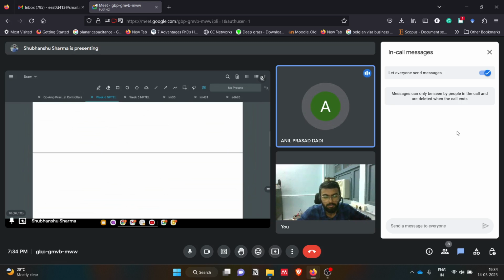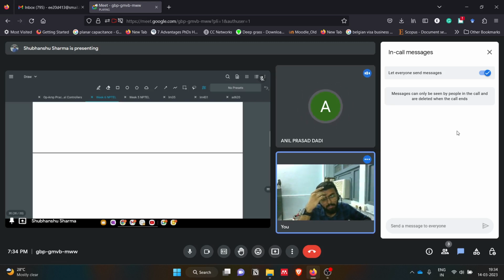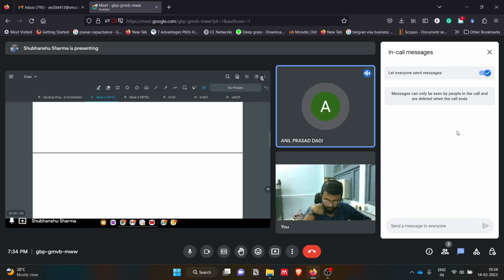Yes, sir. In fact, when I simulated it, I got the output as minus 3. And when I used the superposition principle, assuming one input is available at one time, I got the output as minus 3. But the answer is being given as plus 20. Did you assume positive feedback, plus or minus? Did you apply the positive feedback in the simulation? Yeah, I have connected as it is in the question, the way the circuit is given. I got the output as minus 3, and even manually I calculated applying superposition principle, under the assumption that the open loop gain is very large.